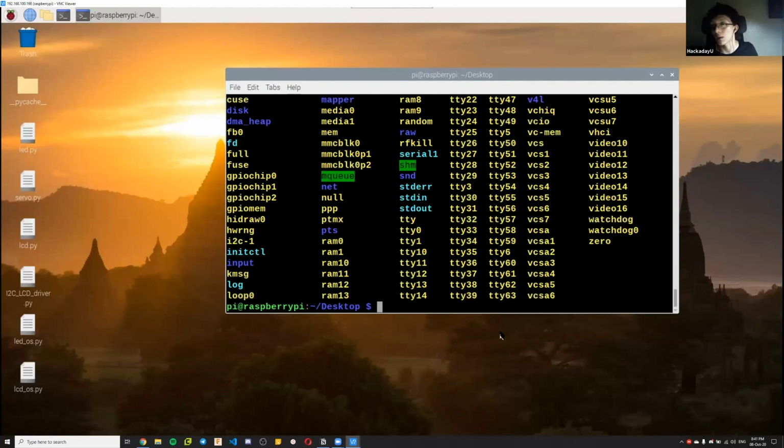It's going to take two GPIOs and make them an I2C bus. That usually happens if you need to put more than one device of the same kind, because they usually can't come with the same address. Some manufacturers know about this, and they put some pins so you can change it. So if you're going to be using more than one, you can change which address is going to appear on that device, so you don't have that problem.